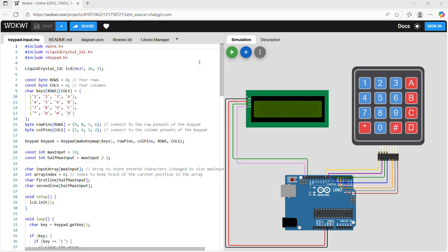Here the keypad is arranged as a 4x4 matrix with 16 keys. When a button is pressed, one specific row and column get connected. The microcontroller scans each row and reads which column goes high to detect which key is pressed. The detected key value is sent to the LCD through the I2C communication line. The LCD displays the character or message instantly.